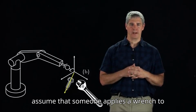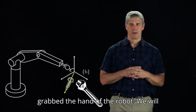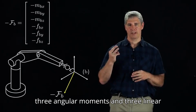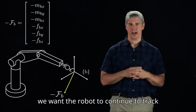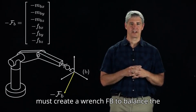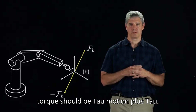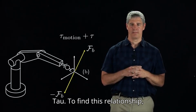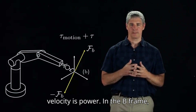Now assume that someone applies a wrench to the hand at this instant. Perhaps someone grabbed the hand of the robot. We will call this wrench minus FB, consisting of 3 angular moments and 3 linear forces expressed in the B frame. If we want the robot to continue to track the planned trajectory, despite this disturbance wrench, the robot's motors must create a wrench FB to balance the disturbance wrench. Therefore, the joint torque should be tau motion plus tau, where we need to know how FB relates to tau. To find this relationship, recall from physics that force times velocity is power.